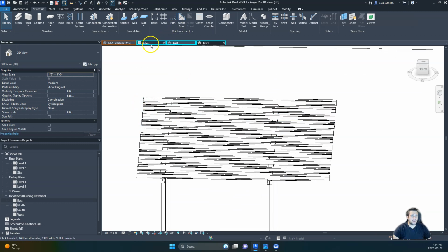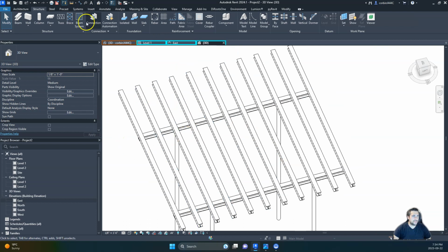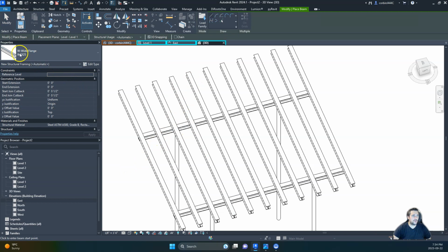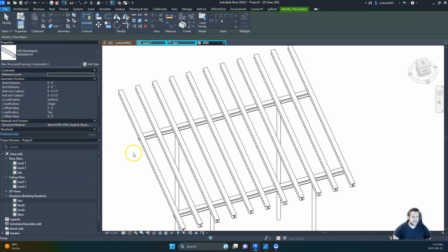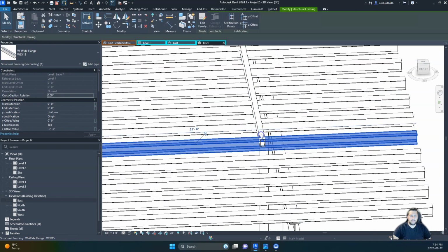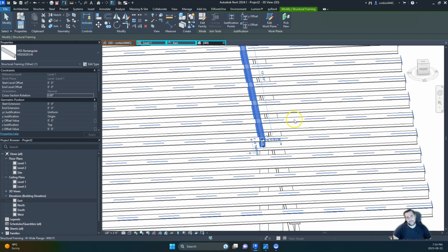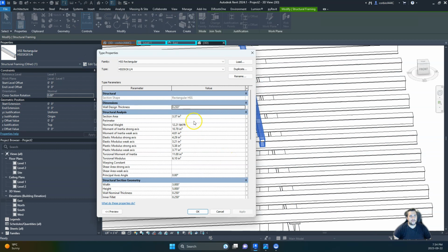So just some complexity here. Say for example, we had a wall in a location. What we'd want to do, whether it's perpendicular or parallel, is model that C channel on top, or sorry, the HSS on top. So often the engineer will put that HSS on top of the girders underneath just to make sure that load carries down neatly, but if it's not, they often block it.